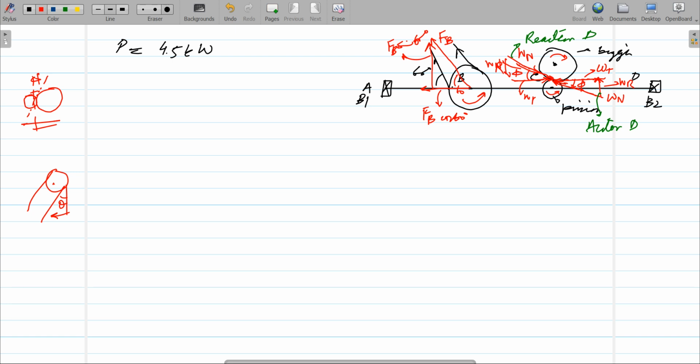But in case of gears, a different configuration is used. That is, you have to draw a normal line which is passing tangential to the base circle, and then we have two components. One is called the radial component, second is called the tangential component, and we have to draw like this. So below this diagram, we have to draw a line so that we can make the components.